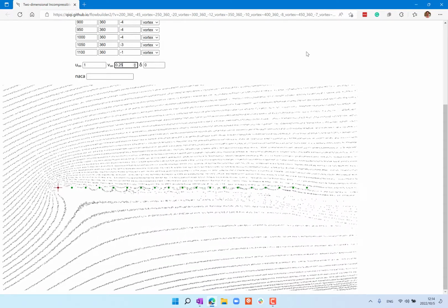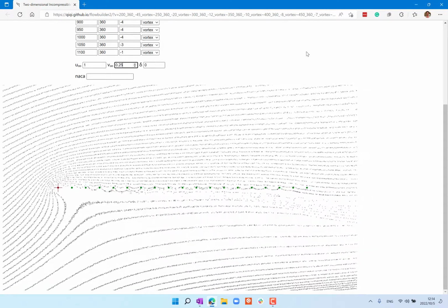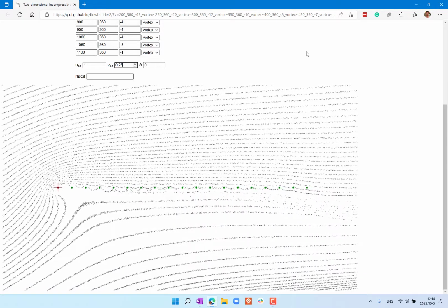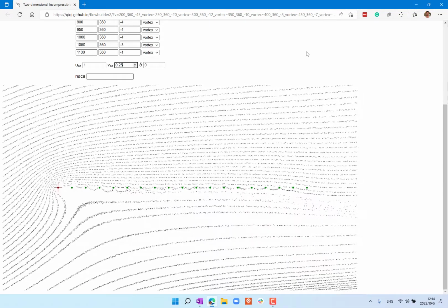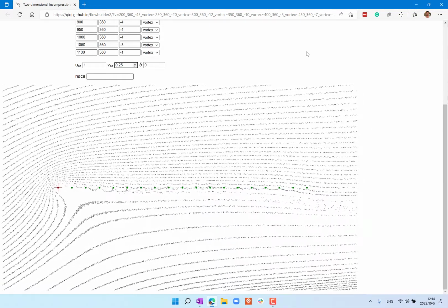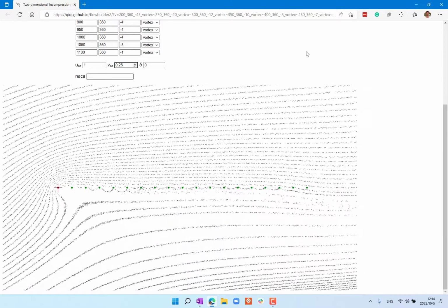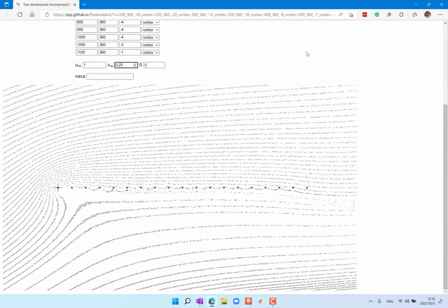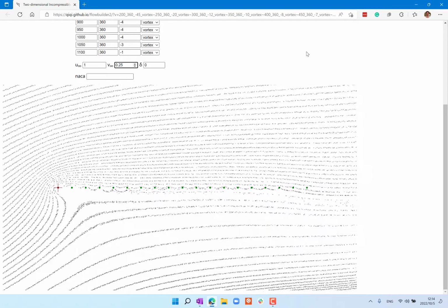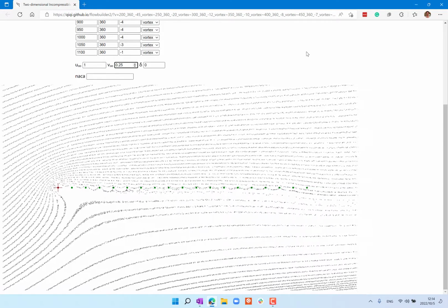But in a calculation like this, and we are going to see later in CFD, computational fluid dynamics, usually the latter is a lot easier. So instead of manually changing the location of all these vortices, it's actually much easier just to change one number, the y velocity, to simulate the angle of attack.